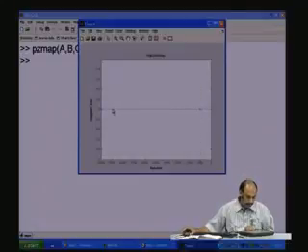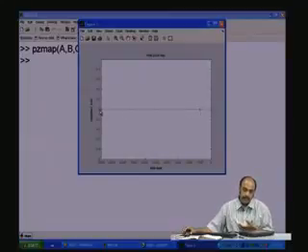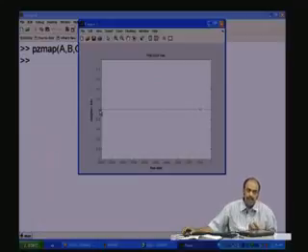The pole of the changed one, which you see here in green, is at minus 10,000. It means that the pole is much further away from the imaginary axis, and therefore, it is faster. As the pole moves more and more away from the imaginary axis, the system becomes faster and faster.